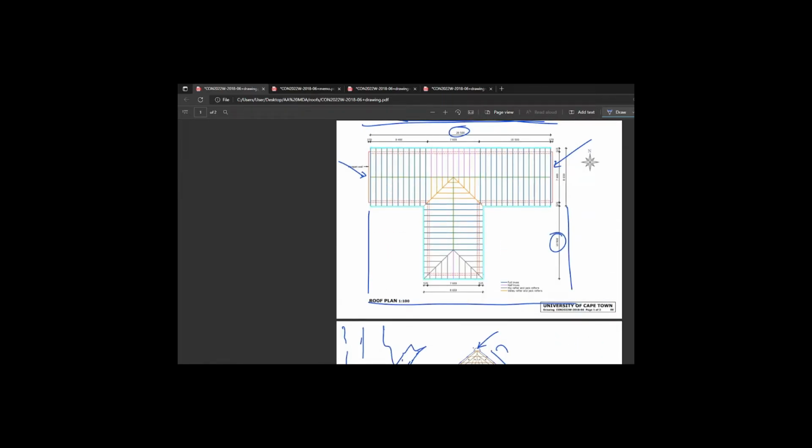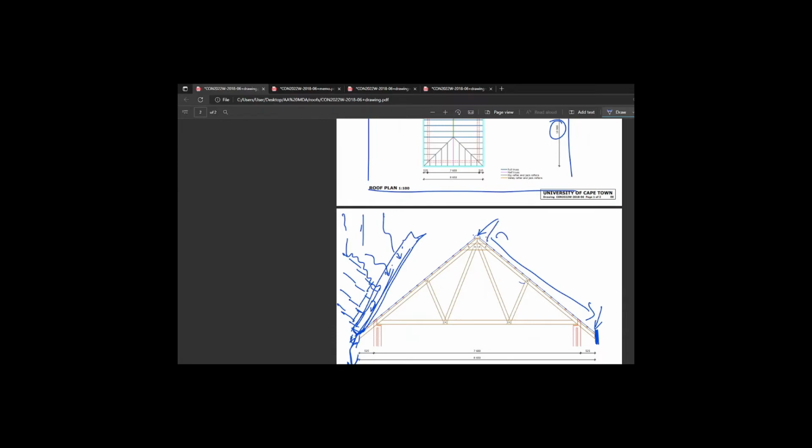And if you've been following, the purpose of a splayed tilting fillet, or just a tilting fillet, is to account for the fact that every tile rests on another tile from the top all the way down until you get to the end. And guess what? The last one is not resting on a tile. Very sad indeed. So we need to help it out.